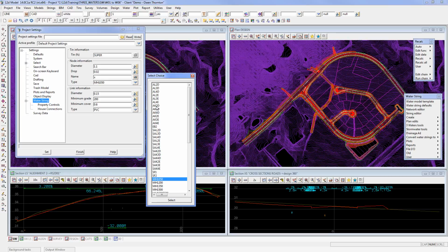It still has to be curb inline. The curb inline, the grate sticks out into the roadway more and causes a cycling hazard more than the lip inline does. And it also has less inlet capacity than the lip inline. So the lip inline tends to be preferred these days in Queensland.